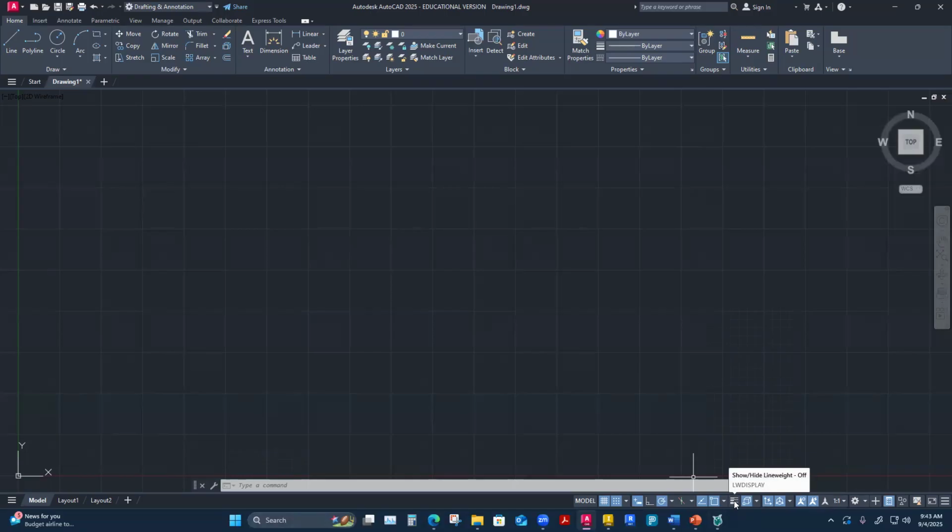And we'll talk about how I differentiate lines, which is generally by color and by the type of line. When I draw in CAD, I don't like to draw with the line weights, because line weights are just the thickness of the lines. So it's hard to snap on lines that have a thickness associated with them. So in my model space, I generally do not like to turn on the line weights and draw with them because they make it awkward. And we can play around with this when we have a drawing to work with.